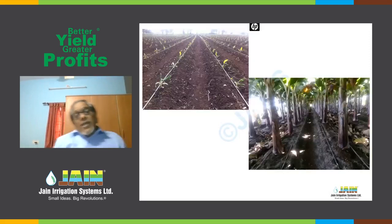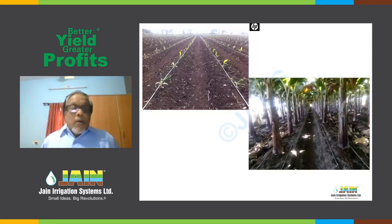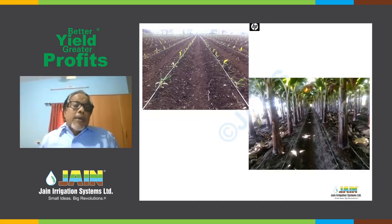Now, this is an interesting case: banana irrigation. Obviously, banana is one of the most drip irrigated crops, and people don't even think about growing banana without drip irrigation. On top, it's clay soil, even though not highly clay, so moisture spread will be very good. For young planted plants, the drippers are very close.